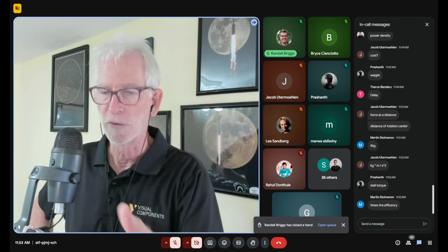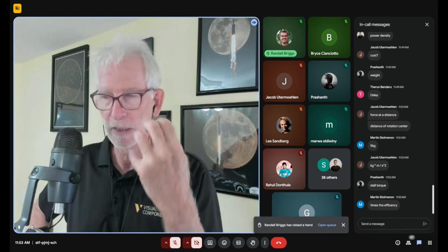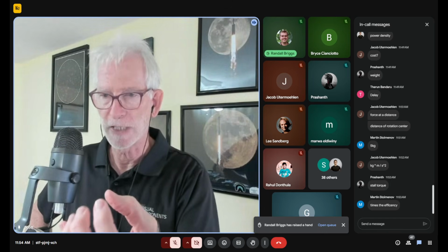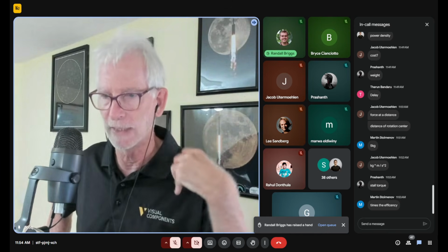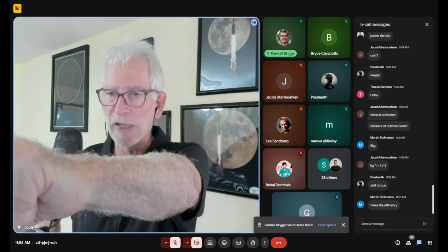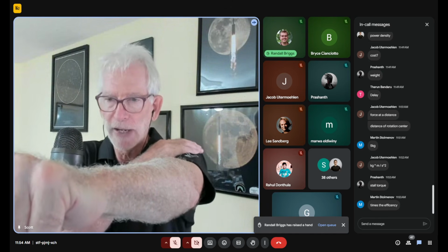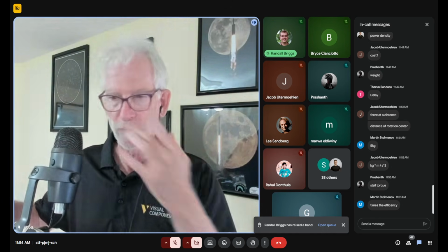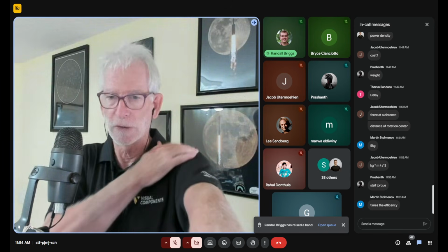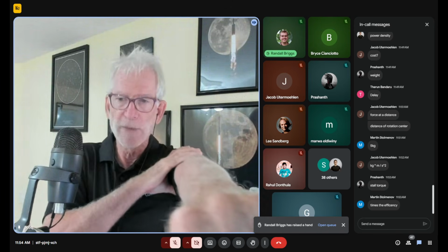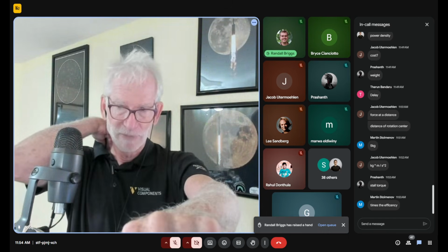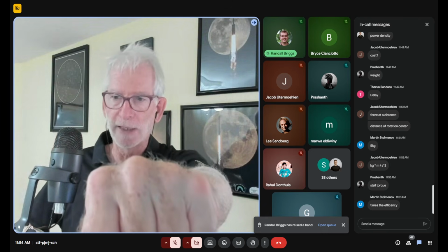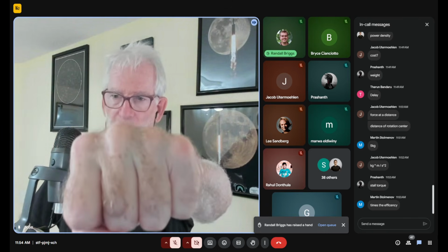And this is why there's this obsession with trying to get the mass of your actuators as low as possible and to bring them as close to the center, or what they would say proximal. Bring them in. We don't want them distal, way out there. So the closer they are, the better. And then we try to reduce what they would call the reflected inertia of what it's going to see. My actuator way back here trying to hold it is struggling, and it probably would not be able to hold that amount of payload because it's got to hold the arm already.